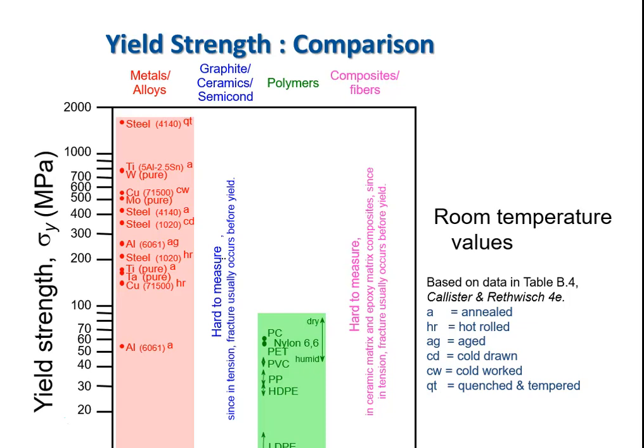So we're seeing a different order of magnitude versus what we saw with elastic modulus. Now we're reporting sigma y in megapascals, so that's 10 to the 6 as opposed to gigapascals, 10 to the ninth. Going over a bigger range for metals, so we go above 1,000 to about 50. Aluminum has a much lower yield, and again that's annealed aluminum.